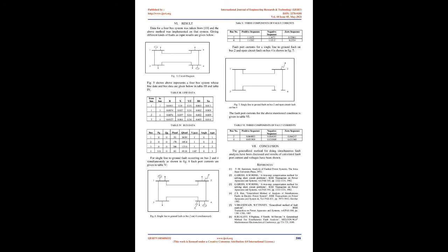The admittance matrices formed here are sparse in nature. The computation time is saved using the admittance matrix in load flow analysis. Then these matrices are transformed into impedance matrices for further calculation, as the fault analysis generally uses Z-bus values for its calculations. Once the type of the fault is specified, we can proceed with the formation of the fault port matrix. The fault port matrix is formed based on the method given above.